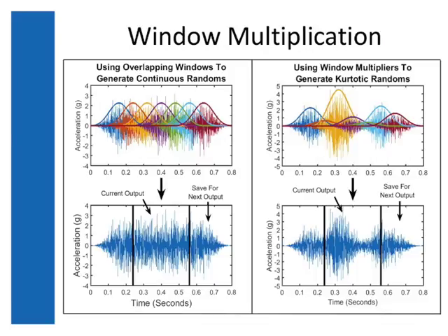So on the left side there, I'm showing an example of how individual buffers get stitched together normally. Note that the length of each buffer is always the inverse of the frequency resolution that you set, because you have to use an inverse Fourier transform to create them. So if you want to make sure that you're turning the power up and down slowly enough, the buffer length is sort of a natural timescale.